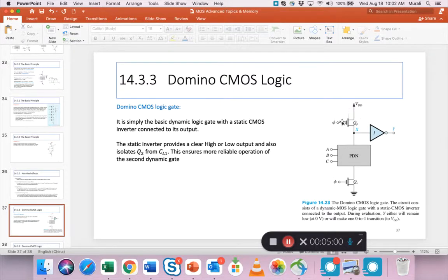It's the same dynamic MOS gate without the PUN and these two extra transistors, but now you put an inverter stage in the middle before X and Y. So to solve the problem, obviously you have to put in more hardware. So again, your cost goes up. This is just a static inverter. It's a CMOS inverter, consisting of both an NMOS and a PMOS device, but a basic inverter. Whatever the input is, the output is the reverse, right?